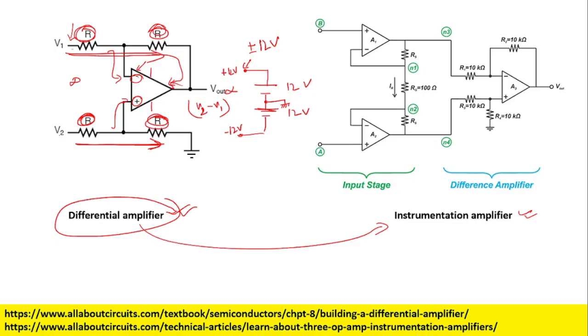That you are supposed to study in class 11, 12. A voltmeter is having a high input impedance because no current is meant to flow through that, right? But in an ammeter, it was being put into series, right? Now, because of that, for current measurement you need low input impedance so that for the measurement of the current you do not disturb the current flow of the circuit, right?